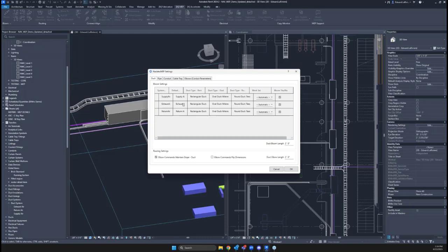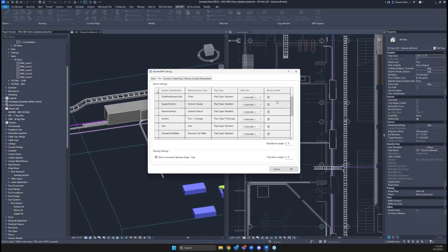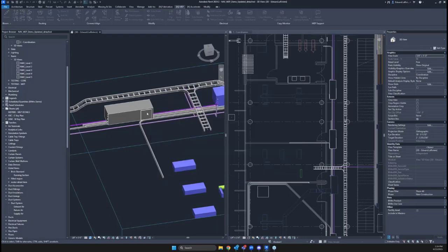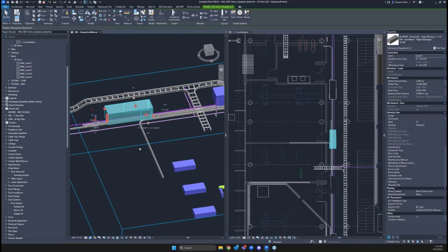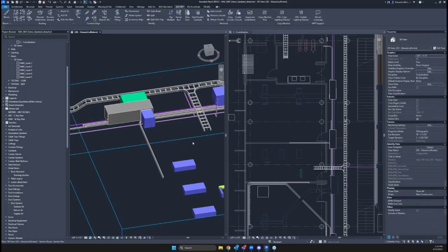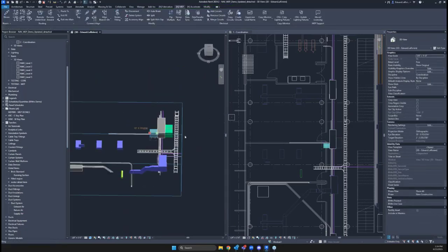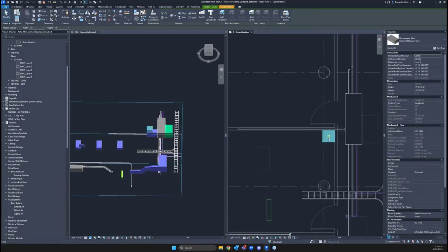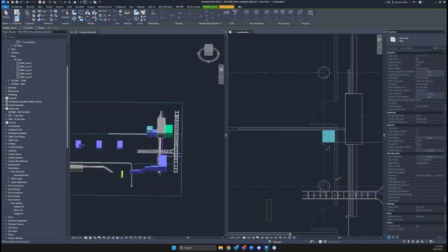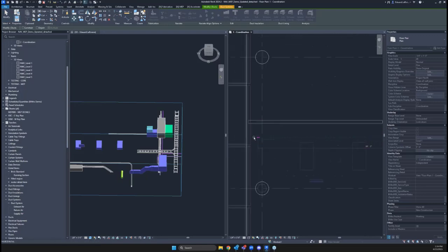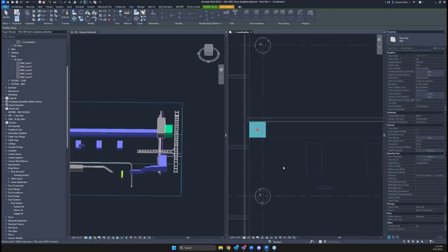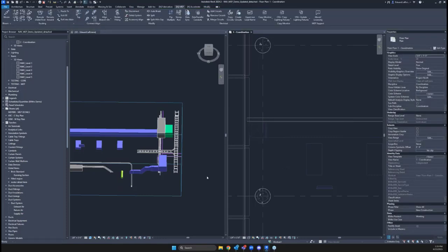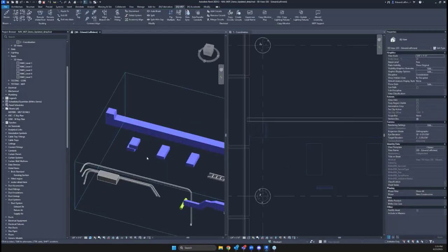I could always go right up to Bloom, find my pipe work, and turn these systems off. So Bloom just will not execute against those pipe connectors. And now I can work with just those ductwork trades that I need to. Maybe I want to do an elbow up over here in 3D to start locating it. Maybe I'd rather jump to 2D to locate it. Really up to you and your workflows. There's not necessarily one specific way to get anything done. I like to say whatever's quickest for you is the correct way.